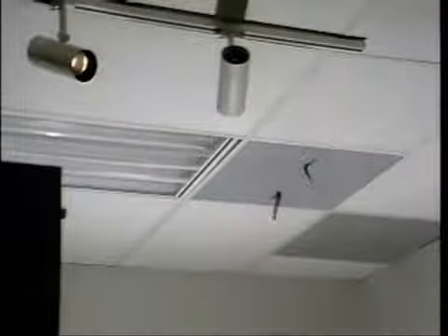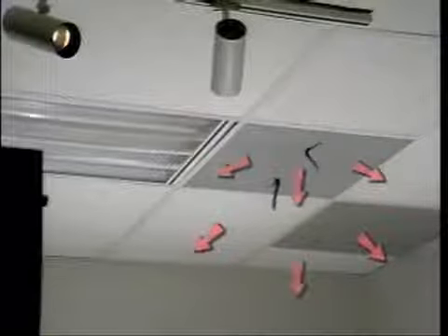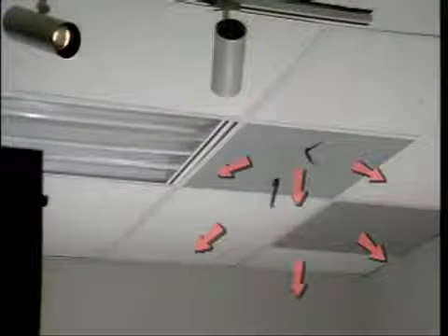Convection heat transfer that's produced mechanically is called forced convection. Many buildings have forced convection heating systems. These systems use fans to force warm air into rooms. The warm air then mixes with the cooler air in the room, and convection heat transfer occurs.